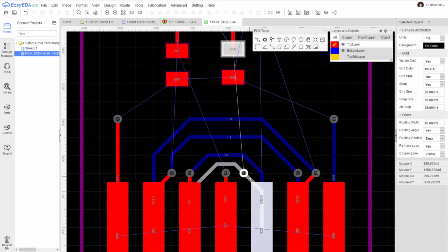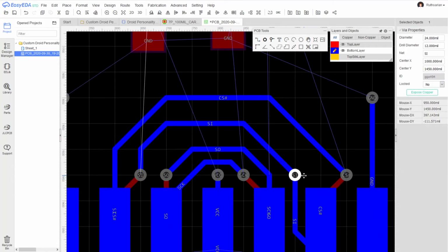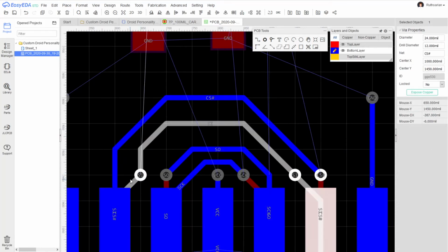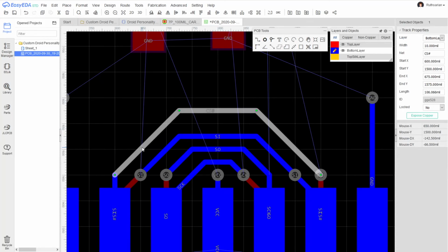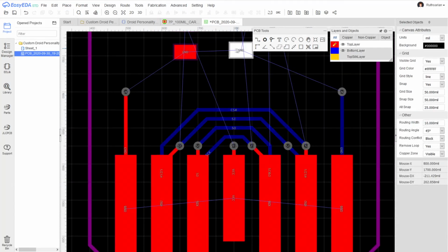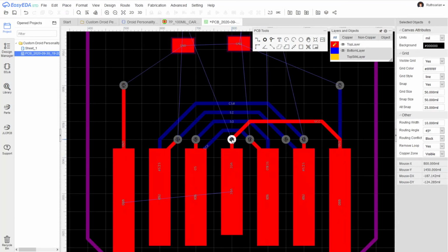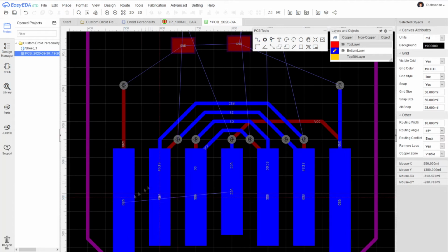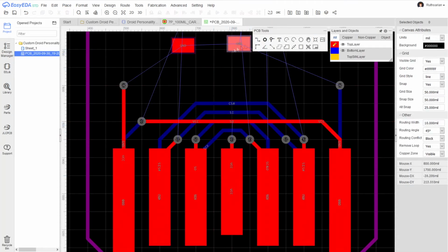And just as it gets close to one of the fingers, use a via to bring the trace from the bottom layer to the top layer and connect it to one of the fingers. So what I'm creating here are these series of what look like arches going back and forth on the bottom layer here. And their purpose is to connect the top and bottom fingers together. That way, once all of this is taken care of, I don't have to worry about it. I don't have to think about it later.